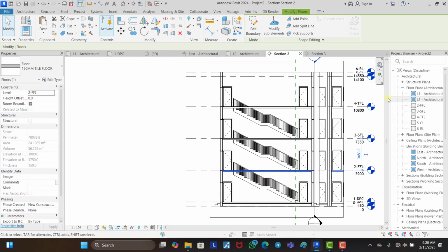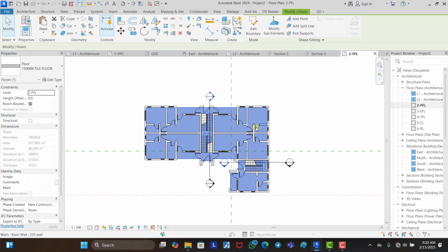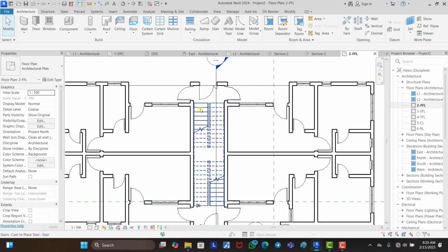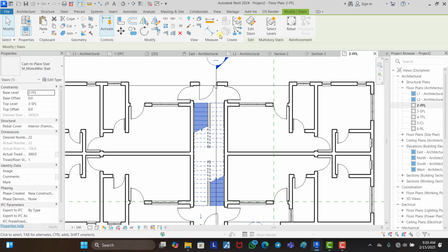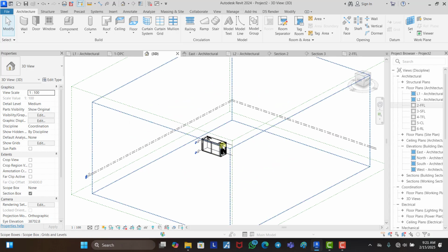So let's go to the first floor level now. Let's see. Now you can see the floor is covering the whole first floor level. We need to create opening around this stairs area for where you can pass through. If you want to understand what I mean, let's click on this staircase and let's section it. Let's cut a section box through it. So see what I'm talking about.